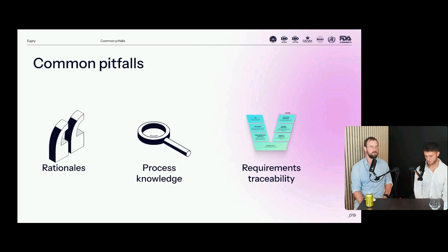That's a very crucial phase. And the auditors get absolutely excited when you can show that you knew what your requirements were and that you're testing those requirements in your mapping. And I would also turn it around and say it's impossible to write a mapping protocol if you don't know what your requirements are. Yeah. Something that we tend to see being added on at a later point, but it is really crucial to have a good traceability between your requirements and what you're actually testing.